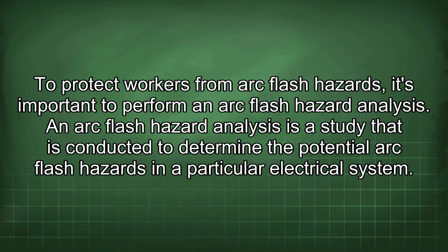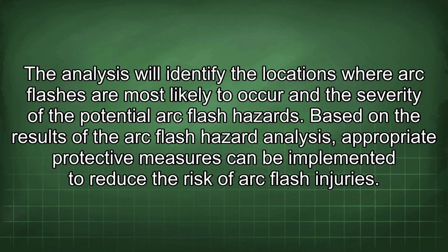An arc flash hazard analysis is a study that is conducted to determine the potential arc flash hazards in a particular electrical system. The analysis will identify the locations where arc flashes are most likely to occur and the severity of the potential arc flash hazards. Based on the results of the arc flash hazard analysis, appropriate protective measures can be implemented to reduce the risk of arc flash injuries.